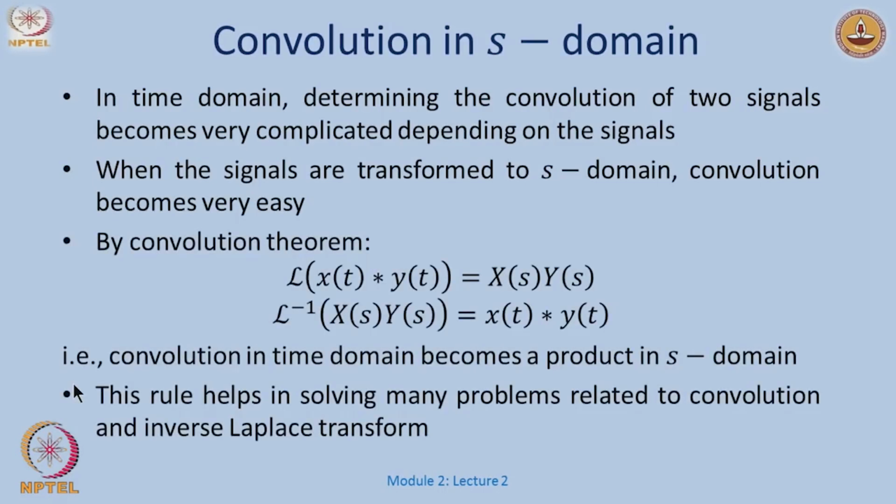Okay. So, what does the convolution theorem say? If I have a signal in the time domain x of t and I want to see its convolution with another signal y of t, it just becomes a simple multiplication of their individual Laplace transforms. The convolution of x of t with y of t is just a very simple multiplication of X of s and Y of s. Therefore, if I now look at it in terms of control, what I had written earlier, I had a u of t here, an h of t and a y of t here.